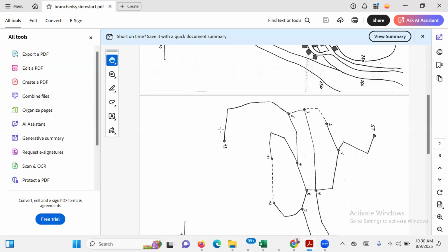And then I also have to know the diameter, which is actually the key parameter you're looking for in water reticulation design. It is to design the pipes. The pipe is your end product, your final output. The diameter of the pipe is your final output, because that's what you're going to procure in the market. If the pipe diameter is not adequate, the water will not flow.